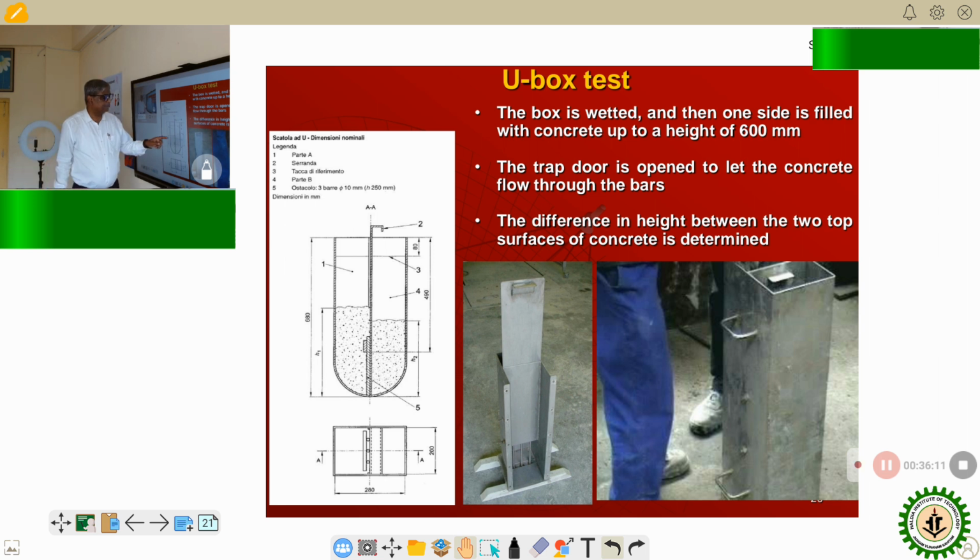So, if it is within the permissible limit, that means your objective of getting the self-compacting concrete is fulfilled. So, this is the way you have to finally say that I have performed this test and the values are within the maximum and minimum limits, and we can declare it as self-compacting. With all these things you have to put in the report.